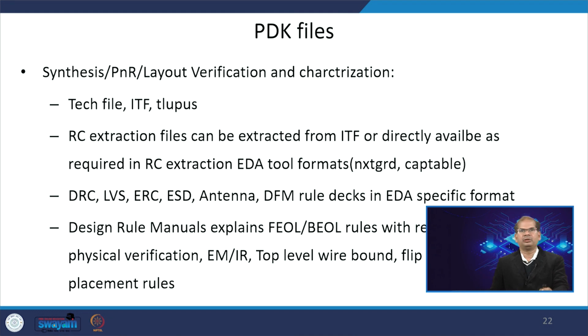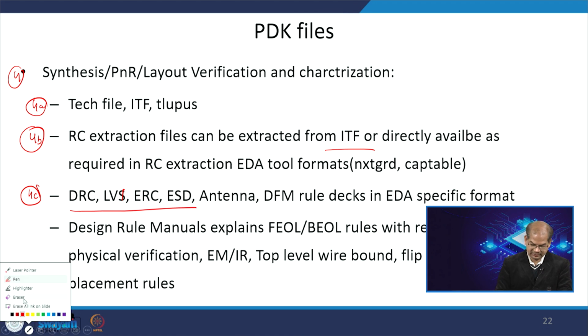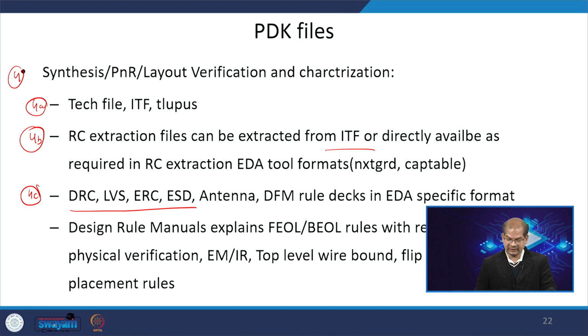Now, we will discuss synthesis related files available in the PDK. 4A will be tech file, ITF file, TLU+, then the RC extraction files extracted from the ITF file. Then the 4C will contain the DRC, LVS related files: DRC, LVS, ERC, ESD, antenna, DFM rule checks in EDA specific format.